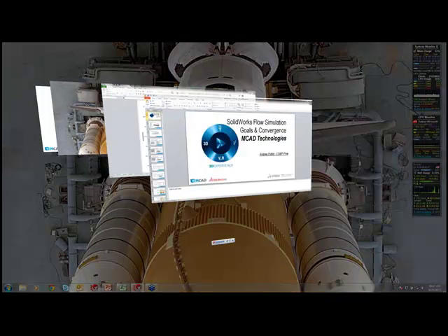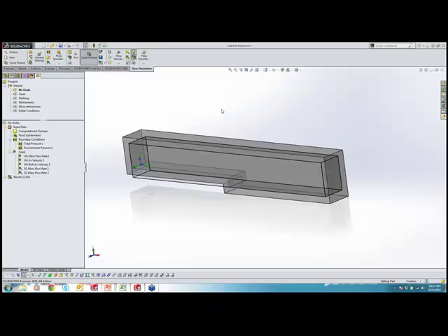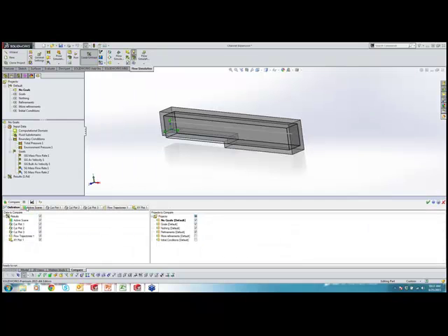If you're not familiar with that feature in Flow, when you're working with something that has more than one configuration or more than one study, you can come up here to this Flow Simulation results, and you can use the compare function. Compare allows us to choose what type of cut plots, charts, ISO surfaces, all of that post-processing stuff that we want, and which projects to apply it to.